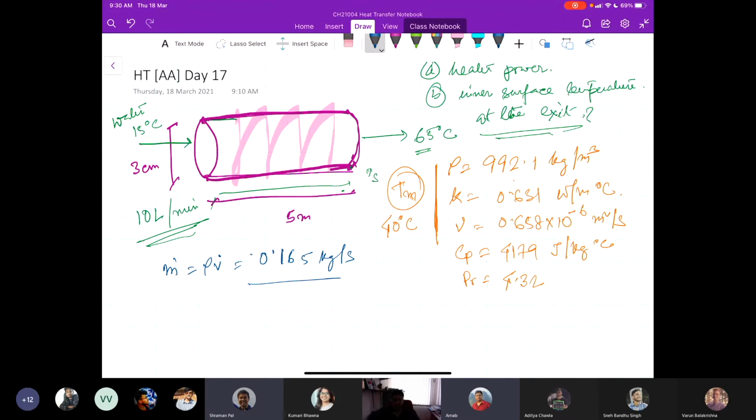Right. Good. So that gives you the Q dot value, which is m dot Cp delta T. The values are already here. So this would be around 34.6 kilowatt. And again, k is small k. So this energy must come from this heater jacket.